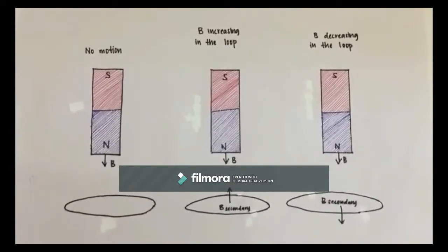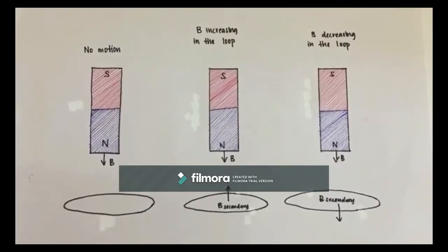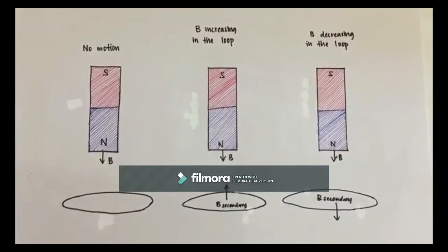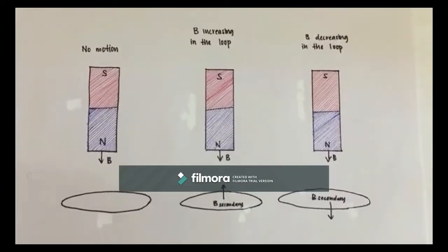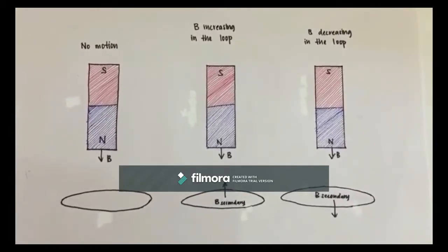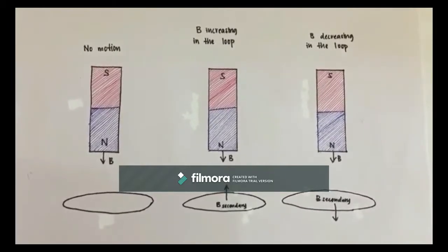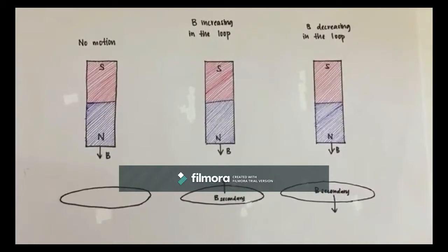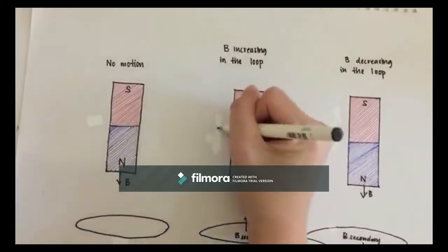This law states that the electromotive force induced in a circuit is directly proportional to the time rate of change of magnetic flux through the circuit. Faraday's law simply states that if a closed loop of wire is placed close to a permanent magnet, then electric current can be induced in the wire by moving either the magnet with respect to the coil or vice versa. Hence, it is the relative movement between the coil and the magnet that matters.